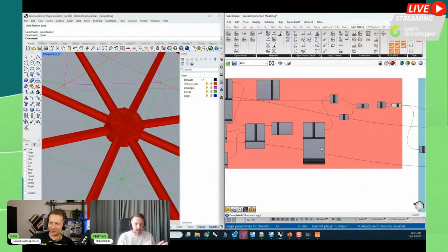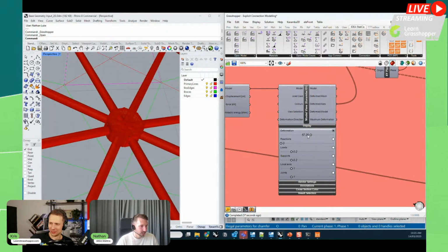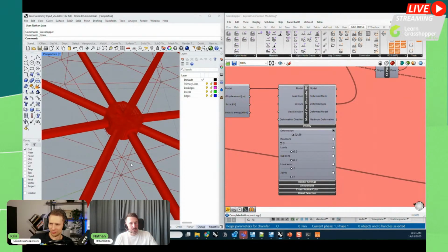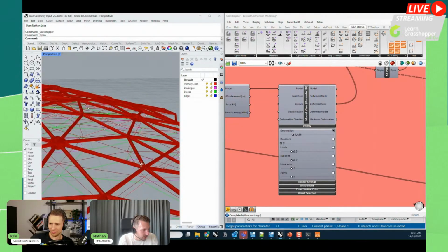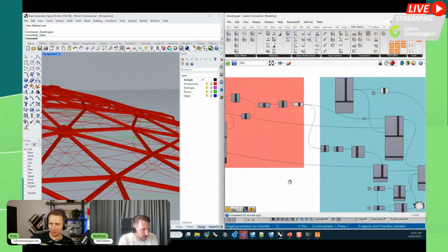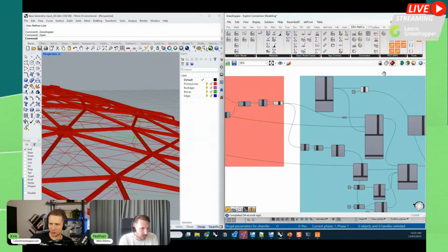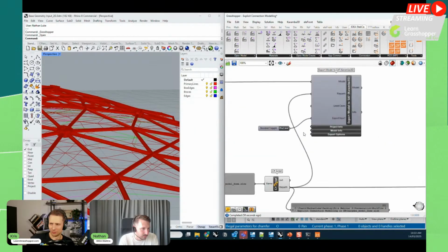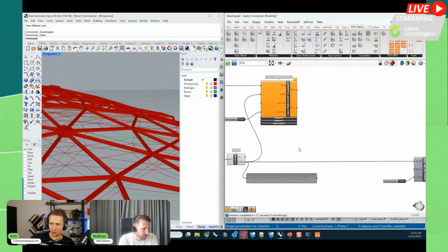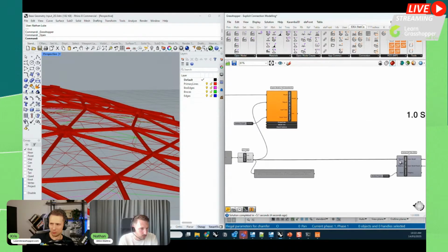So basically, I can go back to the Karamba model. I can change this. This is just changing the deformation or the basic form finding. So you can kind of see how it's moved from that position of where my IOM model is at the moment. And then once I redo that, or re-export that SAF model, the IOM model will, or the connections will be basically automatically regenerated.